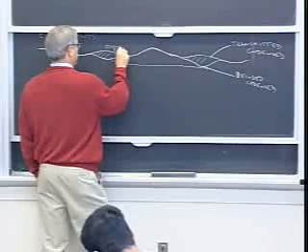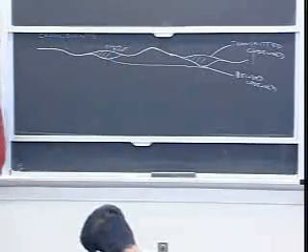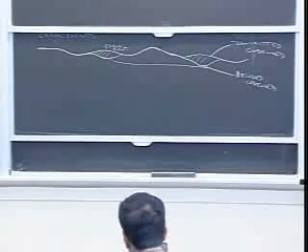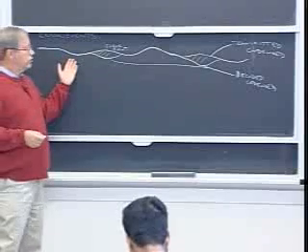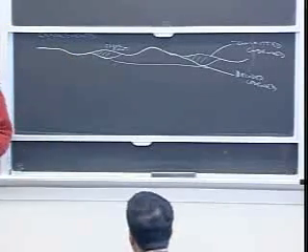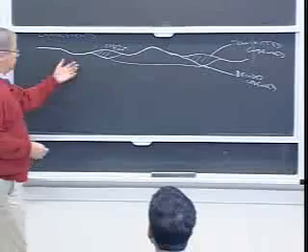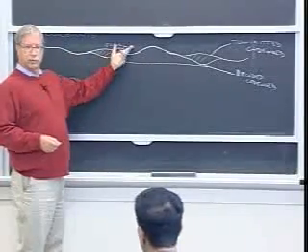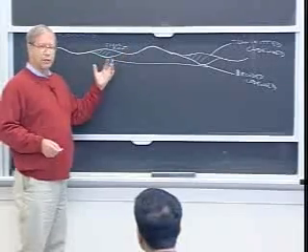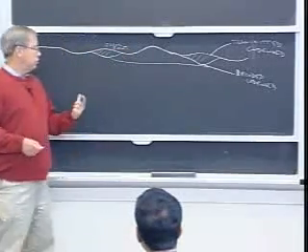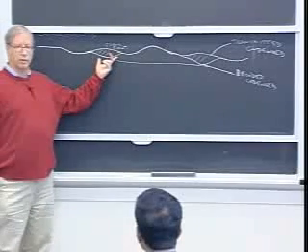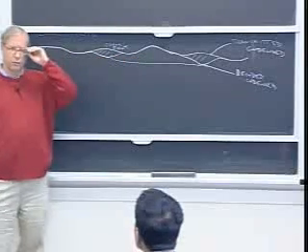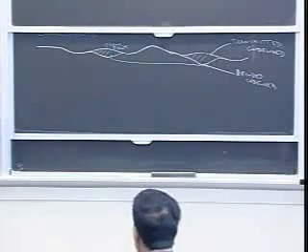So what I'm illustrating is a case when we had two disjoint error events. Is that concept clear? We're going to draw the trellis paths corresponding to the transmitted code word and the decoded code word. Wherever they diverge over a period of time, we're going to call that an error event. But eventually they will reemerge again. It could be a short time, but it can't be any shorter than the constraint length plus 1. That would be the minimum length error event. It could be a longer time, unbounded actually.